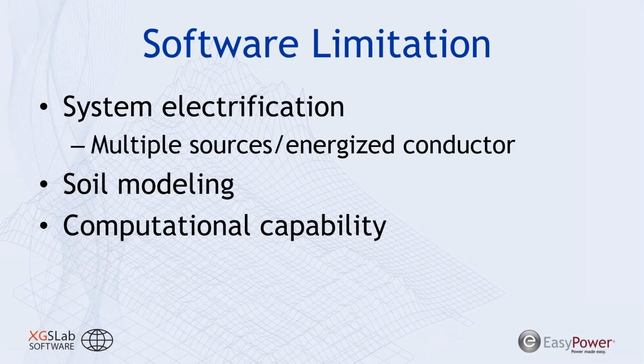Whether that requires you to analyze 3 layers, 5 layers, 10 layers of soil, probably not 10 layers, but you need to be able to consider that, or maybe it's just multi-zone analysis. It really depends on what your soil resistivity information dictates is necessary for an accurate analysis.